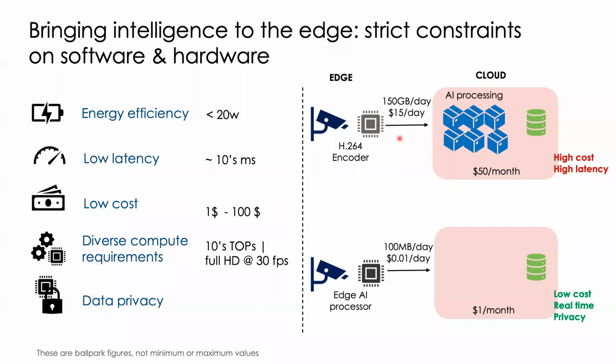By some measures, in this case, we are taking a modest estimate of, let's say, 10 cents per GB. This would come out to somewhere around $500 a month for a single camera. On the other hand, if you have an efficient edge device, a chip that can, on the camera itself, process all the information, and then send some metadata off to your cloud, essentially selectively sending some data but largely processing all the information on the device itself, you can completely avoid the AI processing on the cloud, and you're only paying for the storage requirement.